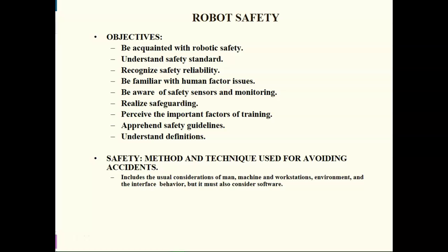Next thing you know, that robot's in motion. You did not even realize that you had forgotten your e-stop or your dead man switch, and now you're going to be hurt bad. So you have to watch out for those sensors and whatever else is monitoring the line, because it can cause a lot of damage, not just to the equipment, but to you or whoever's in the cage with it.